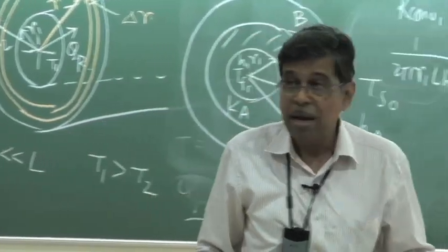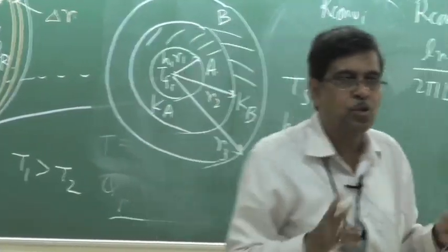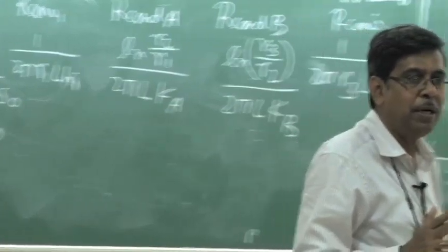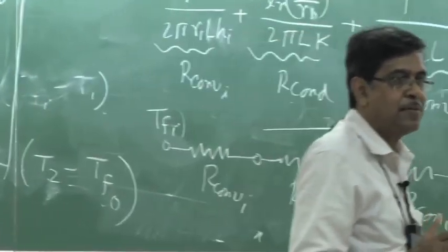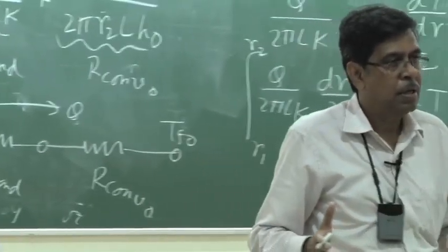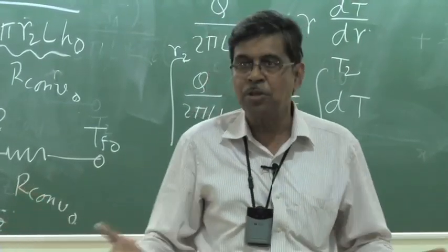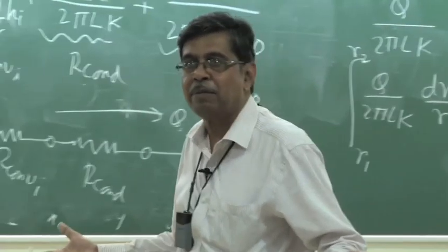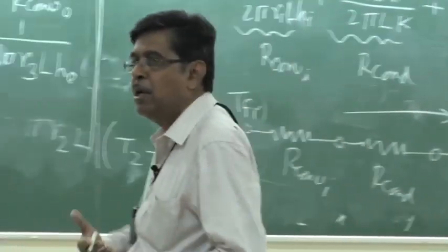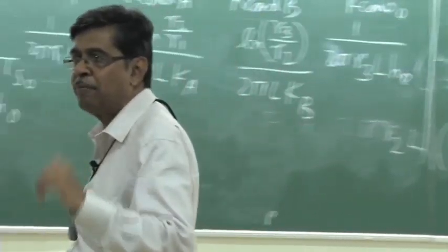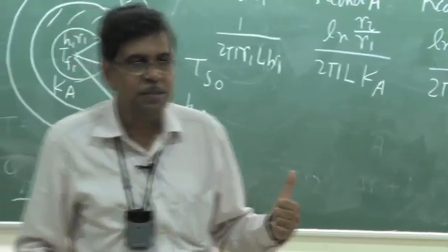Both the things are same. I think for you people, these two things have to be kept in mind, otherwise you will be in trouble. That even in variable area, you will draw a linear temperature profile, then come to the teacher and tell why in a steady state one-dimensional constant thermal conductivity the temperature is linear, why I have not got the mark. So this is very important.